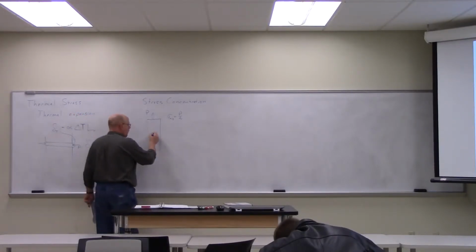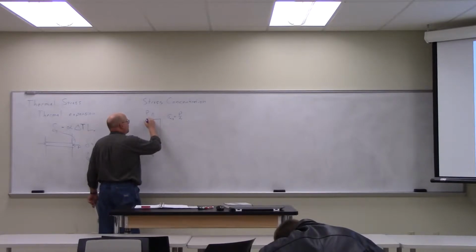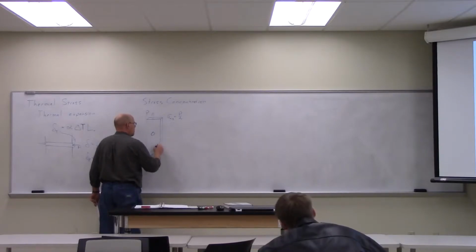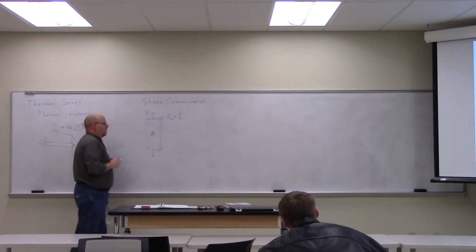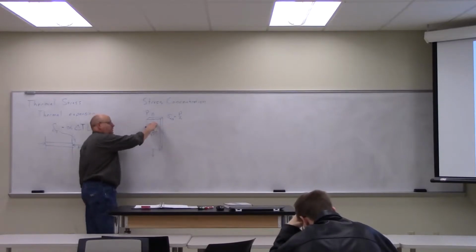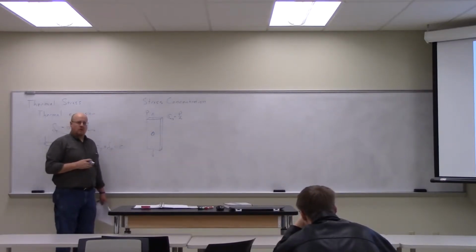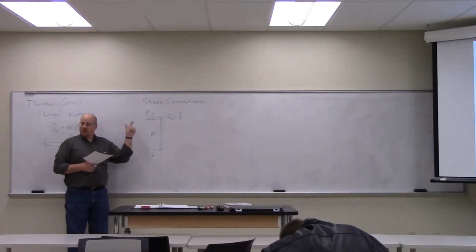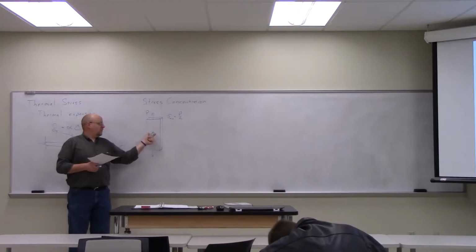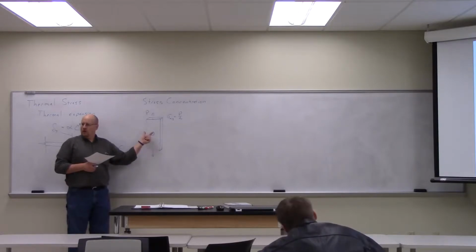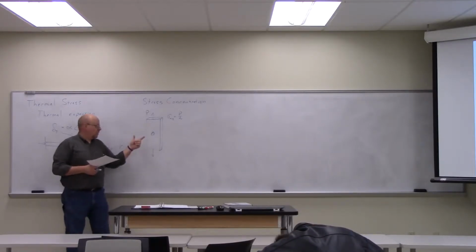But in the center, there's a hole. So if I showed the thing in full cross-section like this, there would be another hole there on the back. You see what I'm saying? The cross-sectional area here is different than the cross-sectional area there. So the stress here is inherently going to be different than the stress up there. But it turns out the stress here is going to be more than just a change in cross-sectional area. There's actually going to be more concentration than just that.